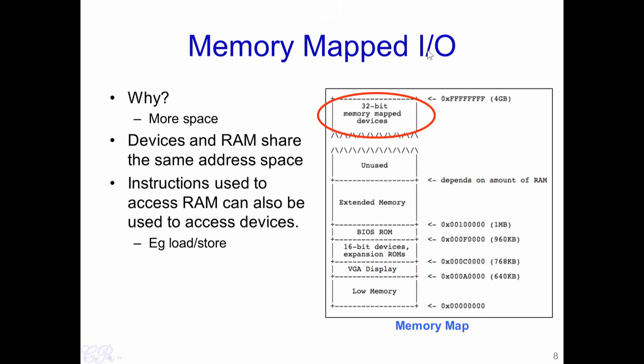In this particular memory mapped I/O, hardware devices would then map into regions in the memory addressing itself. As we have seen before, the RAM or the random access memory of the system would be addressed from the location 0 and extend upwards until the end of the RAM. Typically in the systems of the early and late 90s, we would have something like 256 MB, 512 MB, or at most 1 GB of RAM. So, the space above this was unused.